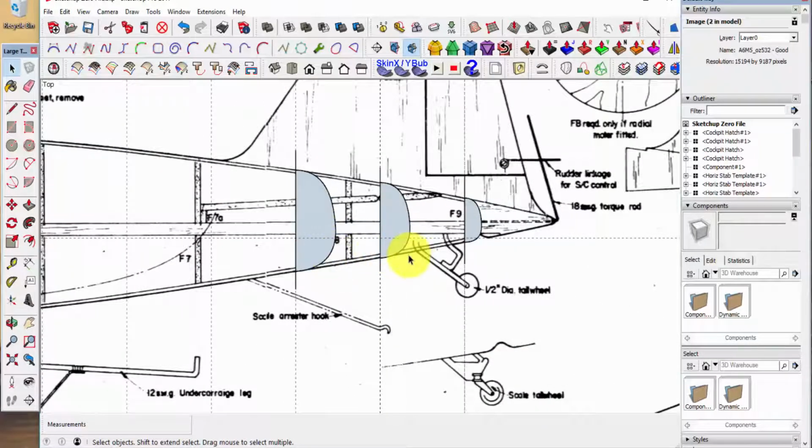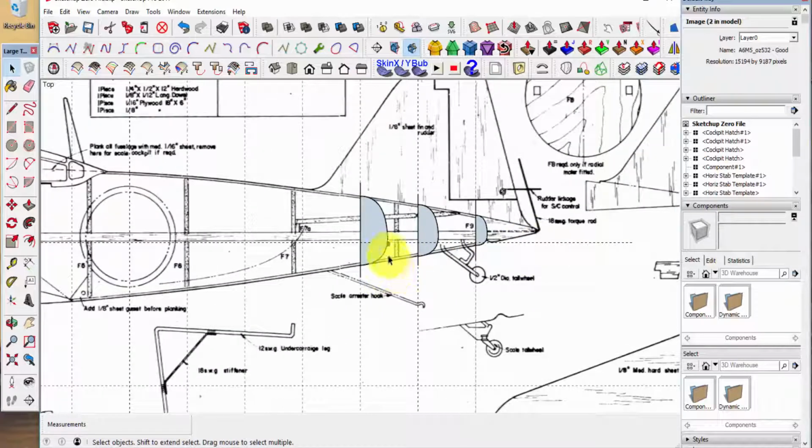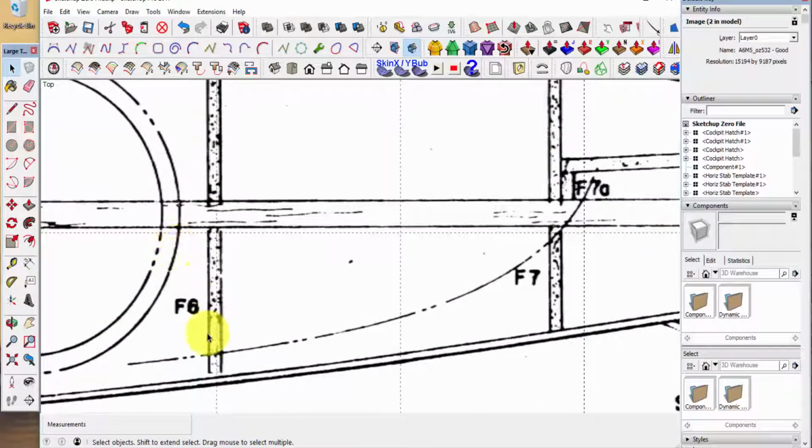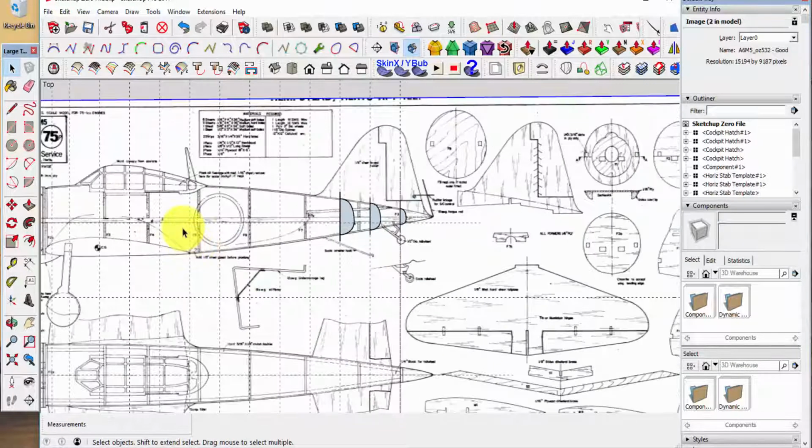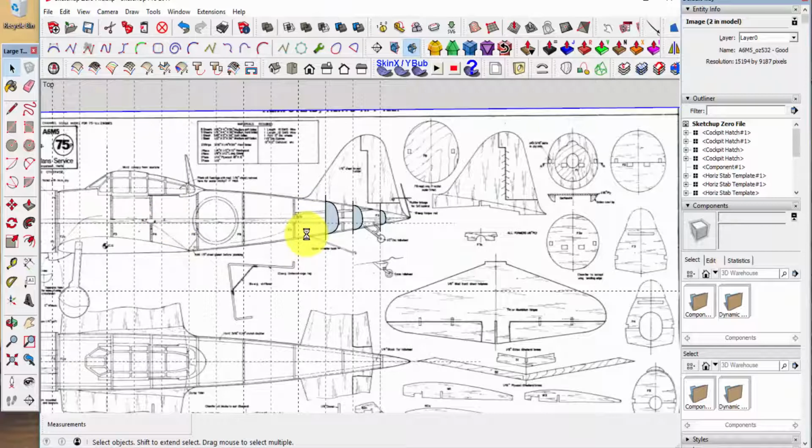And you will see as you do these that quite often you'll have to use F7 here. We're going to use it twice also. And as you can see, we were lucky, F6 fell almost exactly on a segment. But it's very simple. You choose the copied former from the plan closest to the slice, and then you scale it.